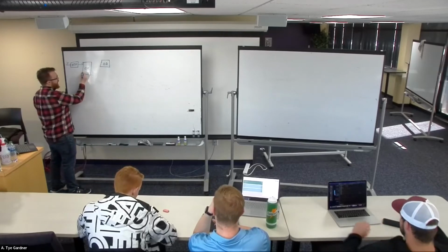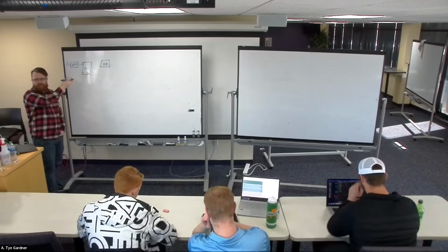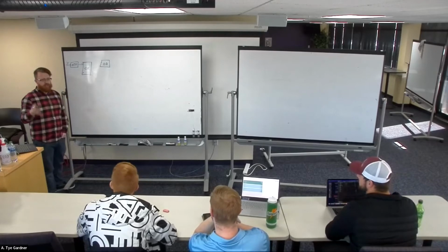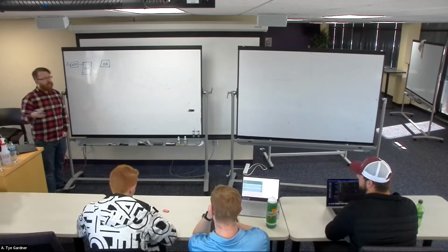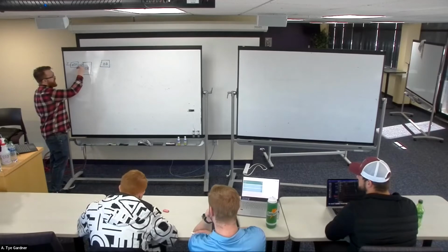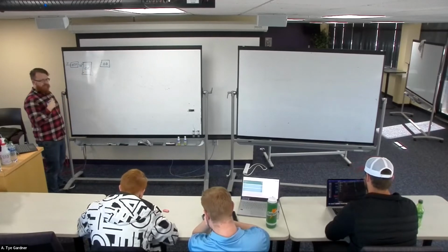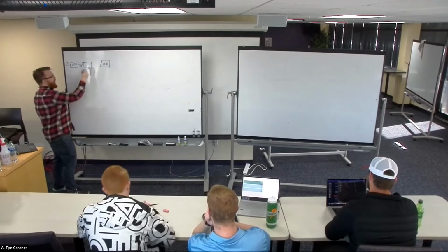Then the current state register, right, is just an array of D flip-flops. So it's clocked. This is the only portion of the state machine that is clocked. And its whole job is to look at this, which is the signal next state, and on the rising edge of the clock, it takes that and pulls it into current state, right? This is basic.